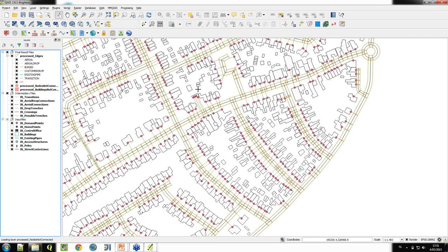So, as I also said during the field survey part of the demonstration, if some buildings are added, you can add these to your input and then do a recalculation. What you can also do is provide spare capacity in your cables, or require spare capacity for your distribution points, for example, so that you can accommodate future changes as well.